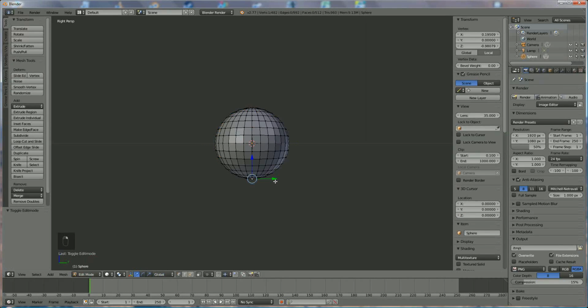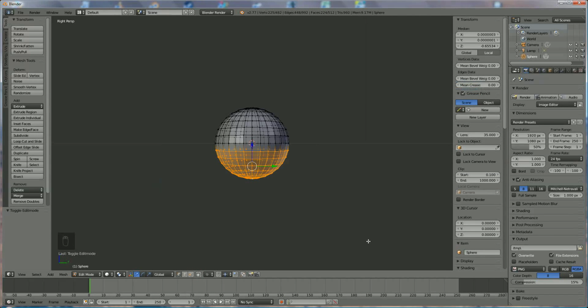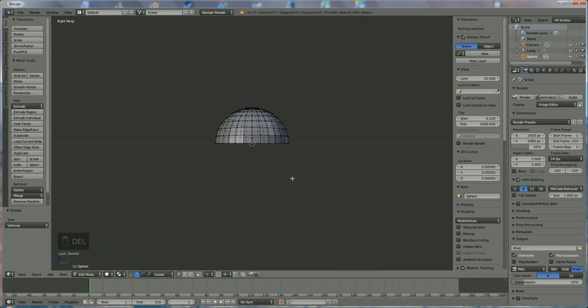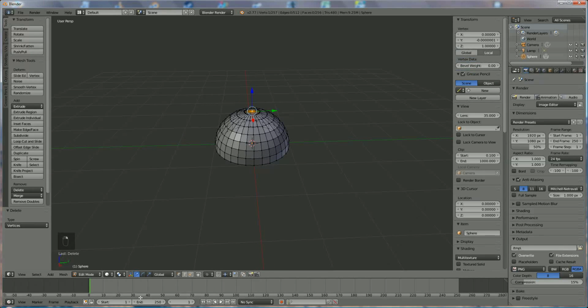Select something underneath, it's not important what, and switch over from the visible parts to the invisible also. Now press B and select half of your sphere. Press delete, vertex, and you have half of your sphere left. Now select the top with point or vertex selection and bring it back straight like this.